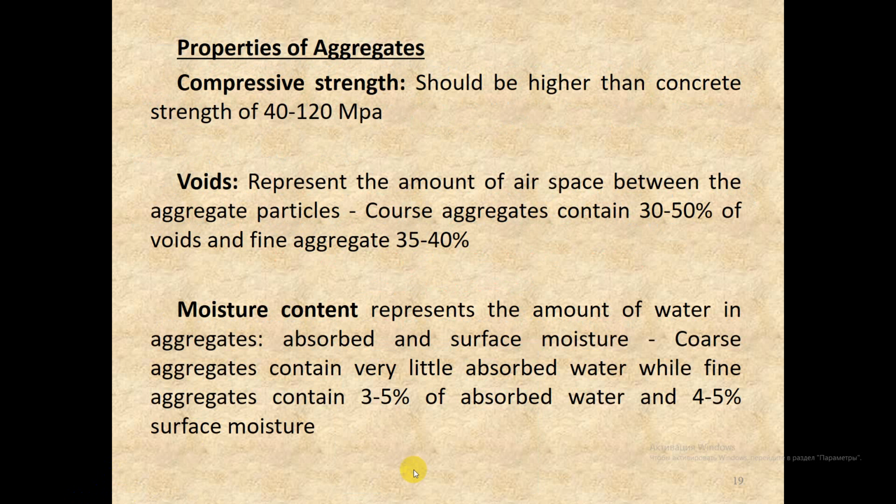When delivered to site, aggregates should be inspected before discharge. It's important to ensure it's not contaminated with silt and clay. Rubbing a damp sample in the palms of the hand will indicate if impurities are in the mix.